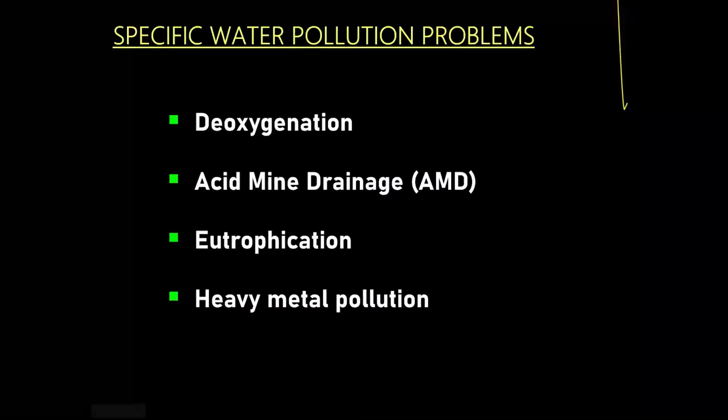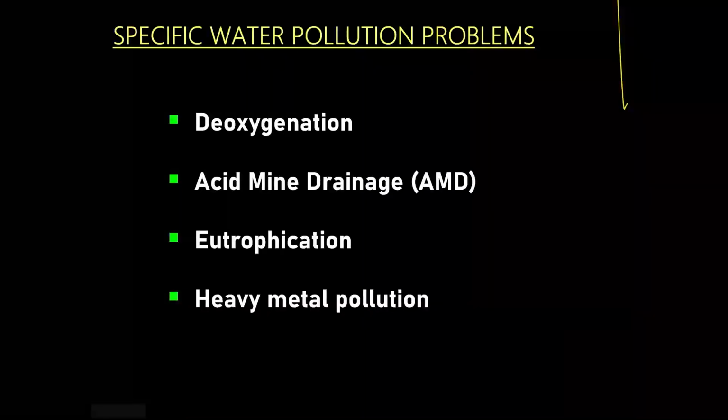Now, the water we use in the mine environment, sometimes we need to do something to the water so that our equipment will be protected. Sometimes we take out oxygen from the water before we can use it for our cooling. The reason being that when the oxygen is still in that water, it can corrode the equipment. So deoxygenation, we take out the oxygen from the water body.